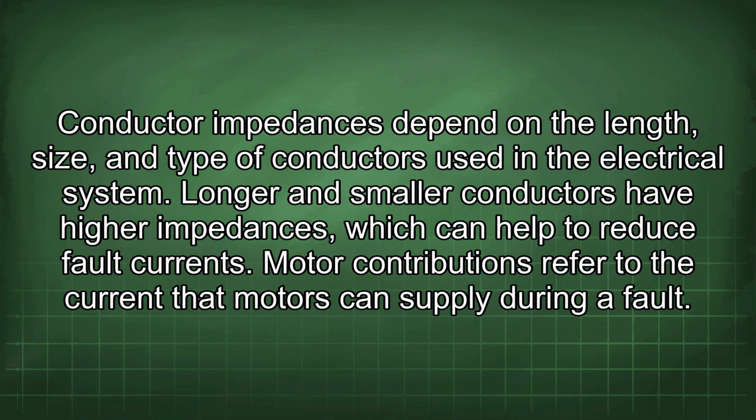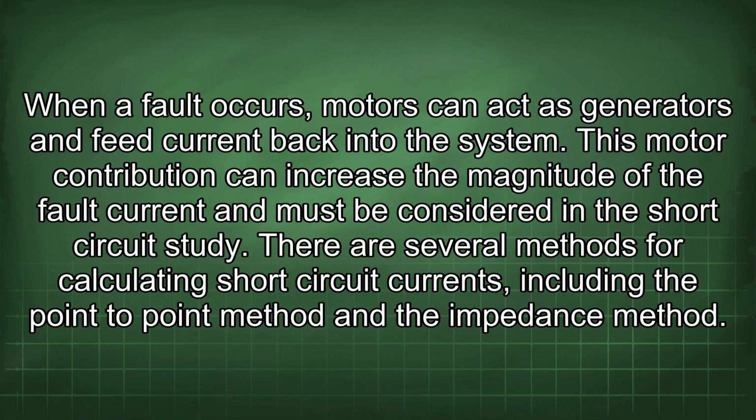Motor contributions refer to the current that motors can supply during a fault. When a fault occurs, motors can act as generators and feed current back into the system. This motor contribution can increase the magnitude of the fault current and must be considered in the short-circuit study. There are several methods for calculating short-circuit currents, including the point-to-point method and the impedance method.